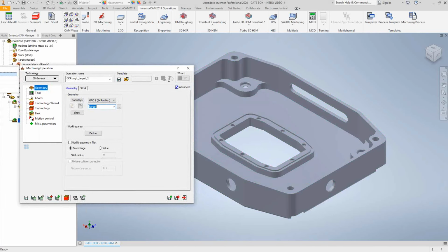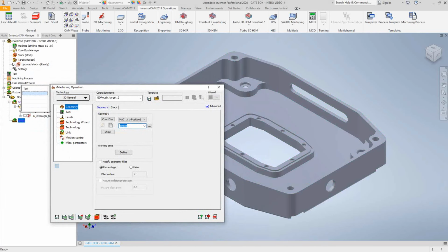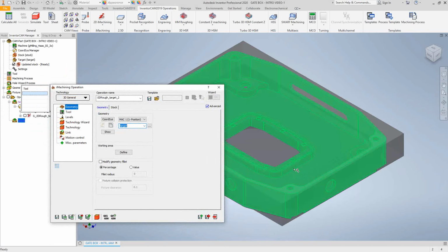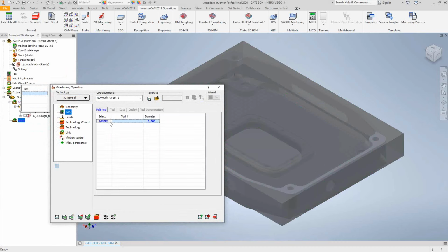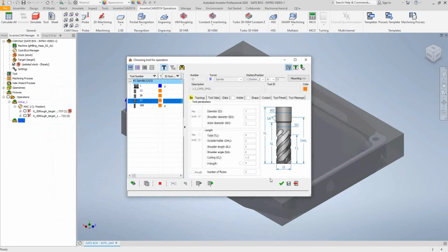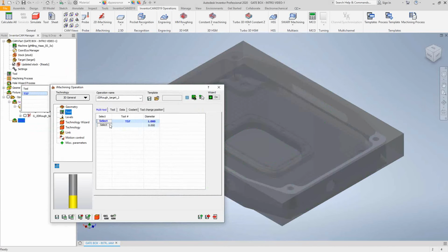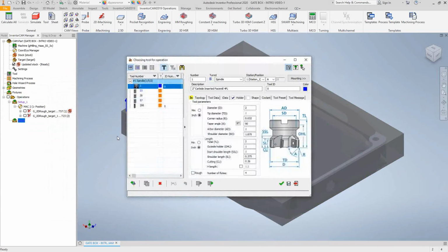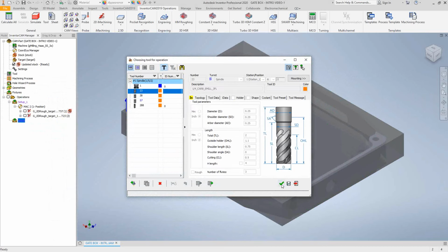The tool has already pretty much machined everything on side 2, leaving behind a lot of material on the edges here and on the inside. So if I just do a simple 3D iMachining here, I'm just going to use basically both tools again. I'm just going to grab this tool, and the 1/4-inch tool.